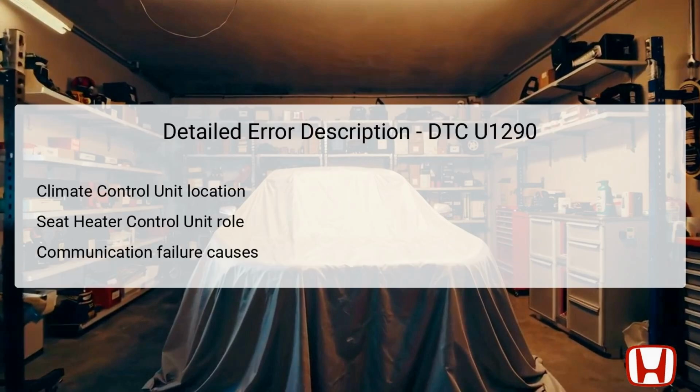The DTC U1290 suggests that there is a communication failure between the climate control unit and the front seat heater control unit. The climate control unit is primarily responsible for regulating the vehicle's internal climate settings, including temperature and airflow adjustments. It is typically located in the dashboard area, housing controls for air conditioning and heating. On the other hand, the front seat heater control unit is responsible for managing the heating elements in the front seats, ensuring passenger comfort.